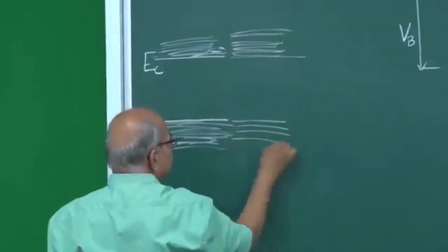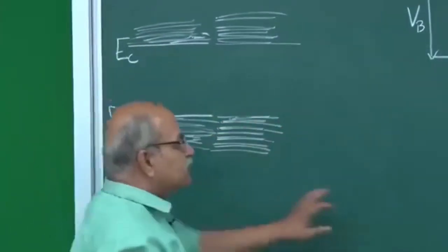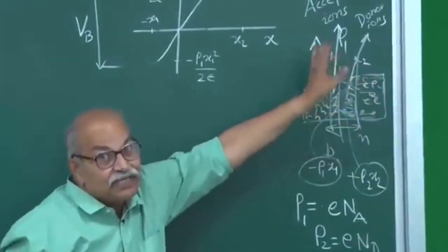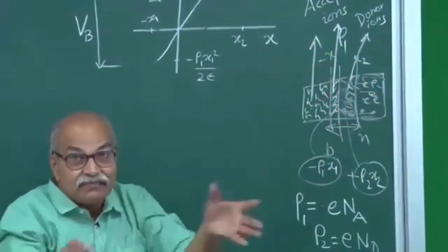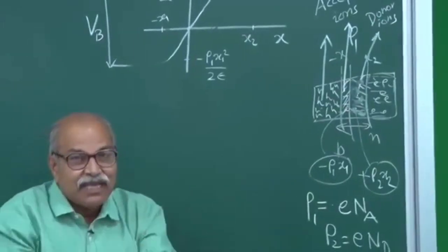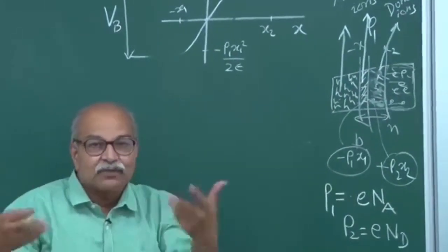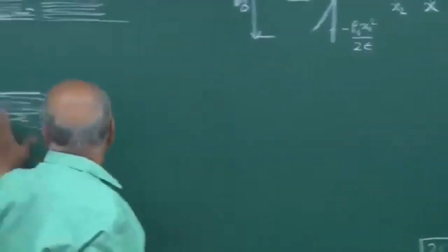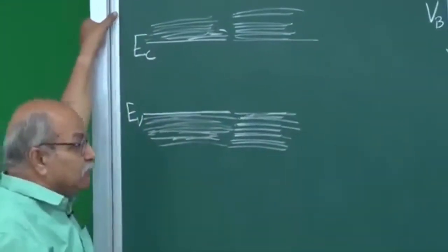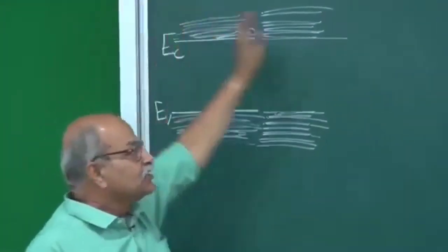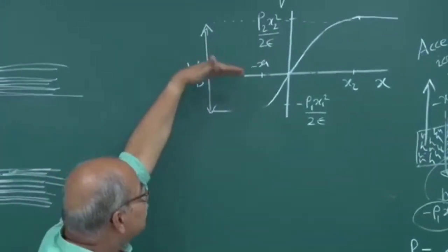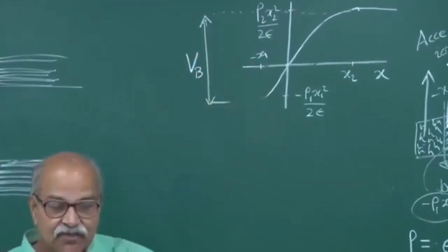Essentially what I am trying to do is I am mapping this p side and this n side. If there is no diffusion, no internal potential difference developed, it's just this much is p-type, this much is n-type, and what is the conduction band, what is the valence band, where are those energies for this entire thing. If you draw it, it should be like this. But it doesn't remain like this because of this. On the p side, the potential has gone down.